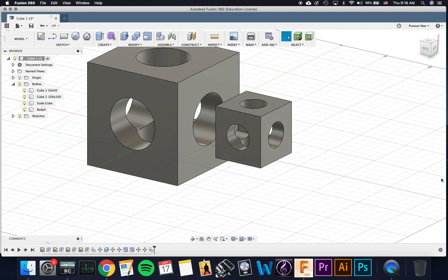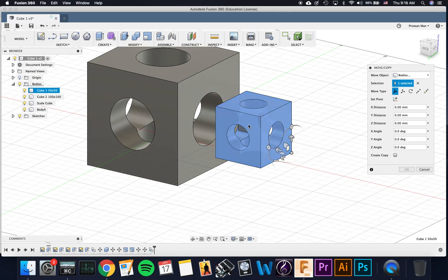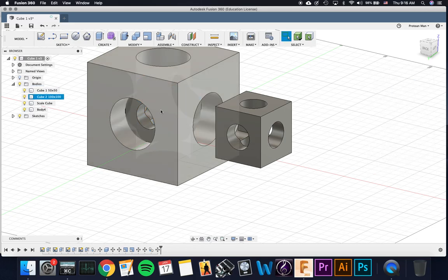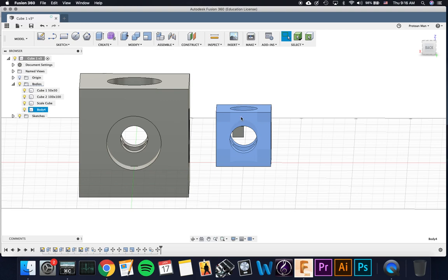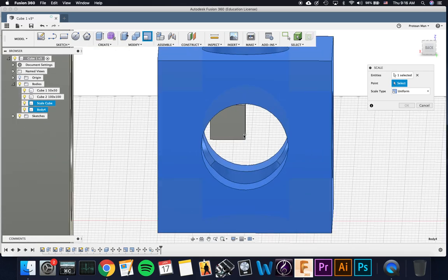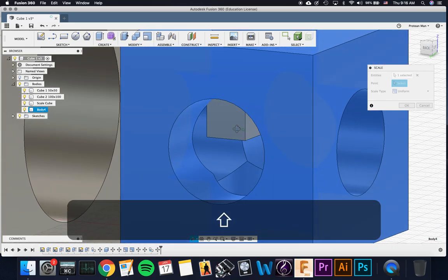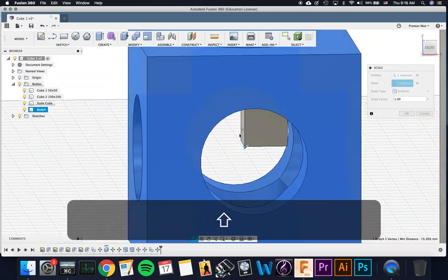So just cancel that, hit cancel or Escape, or Command Z, Control Z back until it's back where it was originally. Go over 100, put it back. So now I have my original cube back there. Now, let's make this one a little bit bigger. Scale. Same thing as before. Take the point, put it on this corner dot of our scaling cube that is in the center of our cube here.